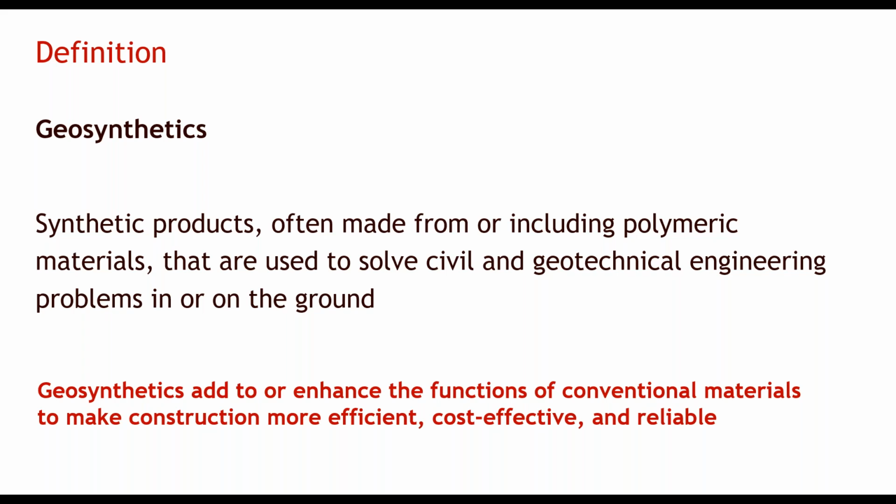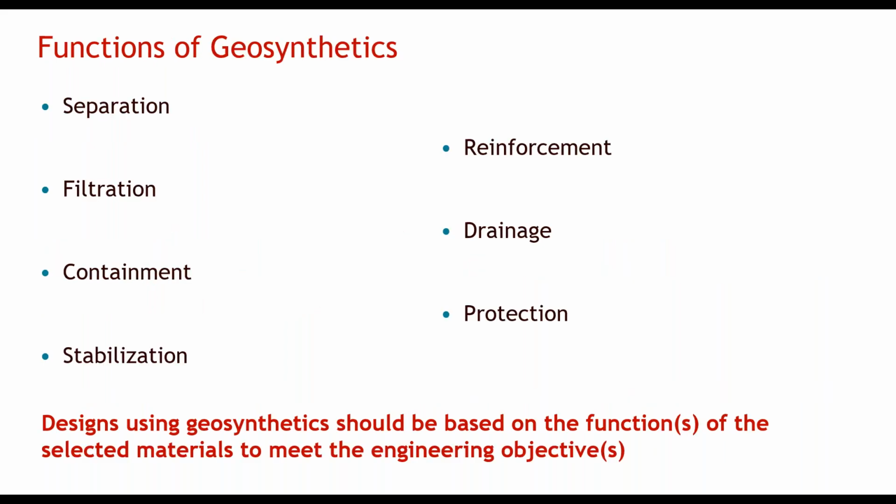Now we'll take a look at the functions of geosynthetic materials. It's critical to understand each of these functions and how they are provided by the various geosynthetic materials. In many cases, these functions can be provided by more than one type of material, and some materials can provide multiple functions. For any project, the key to successfully using geosynthetics is to adhere to the concept of design to function. That is, to thoroughly understand the functions of each material selected, and then to connect those functions to the engineering objectives. This seemingly simple and fundamental concept of design is sometimes, for a variety of reasons, not well applied to the use of geosynthetic materials, which can result in negative results.